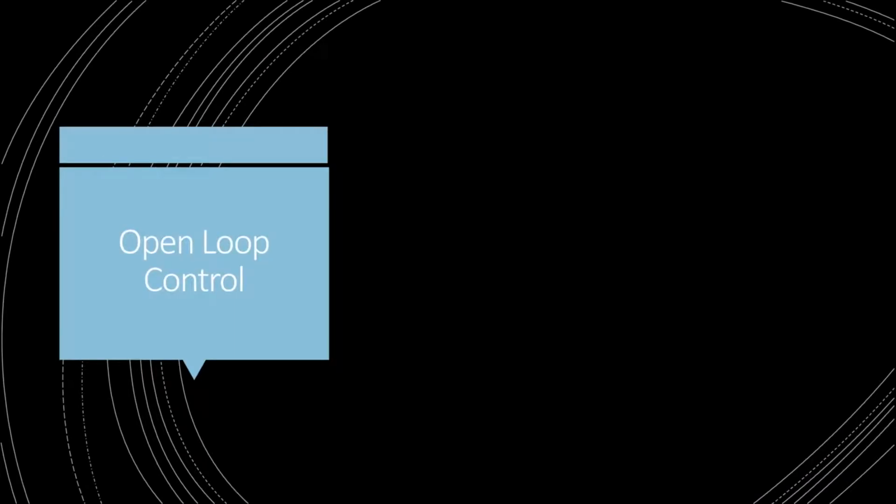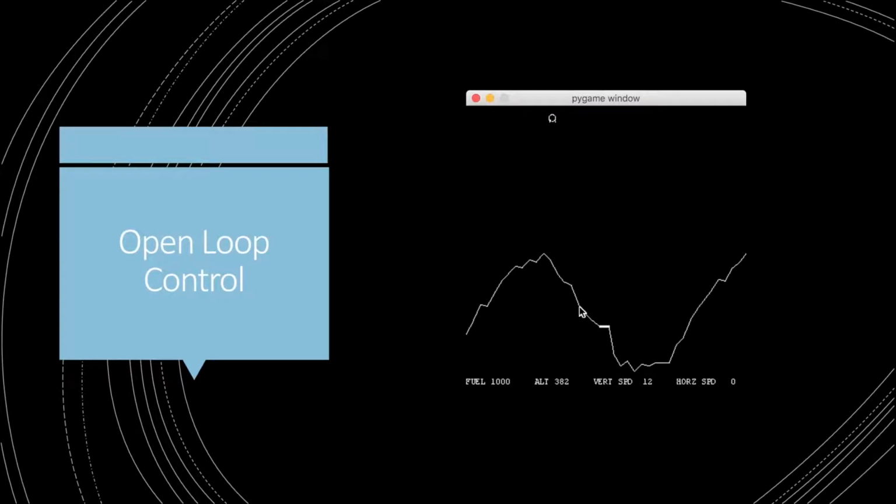Now we're going to present the open loop control. So this is no PID control, just me controlling it. I'm going to start by powering on my vertical thrusters. Since it's manually controlled, I can only have 0 or 100%. I can't do any analog control. I'm also controlling the horizontal thrusters at the same time, but they aren't shown on this program here.